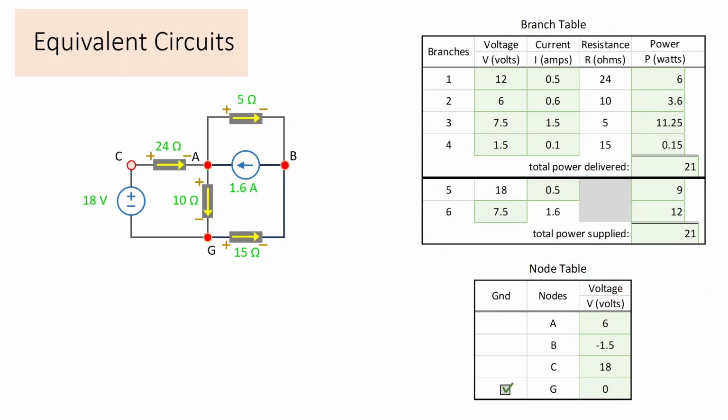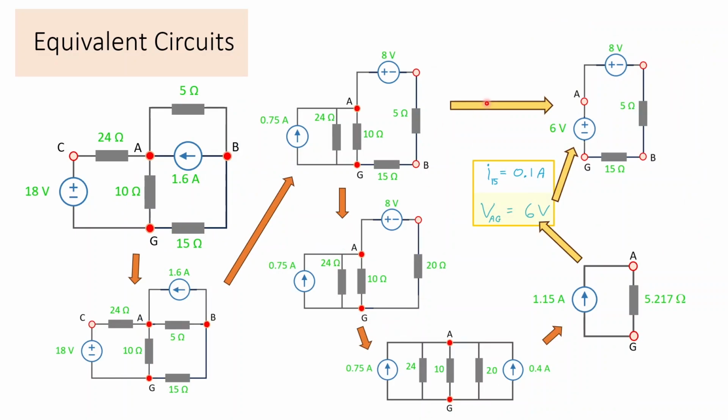And that's our solution, and this was the pathway through equivalent circuits that we took. So as a procedure, equivalent circuits really isn't a procedure, right? You may see something that could be replaced with an equivalent circuit, you try it, hopefully looking to get some sort of a solution. Sometimes with experience with various types of equivalent circuits, especially series and parallel combinations, you can very quickly get a result. But other times, you're better off going to branch current analysis, nodal analysis, or loop analysis.